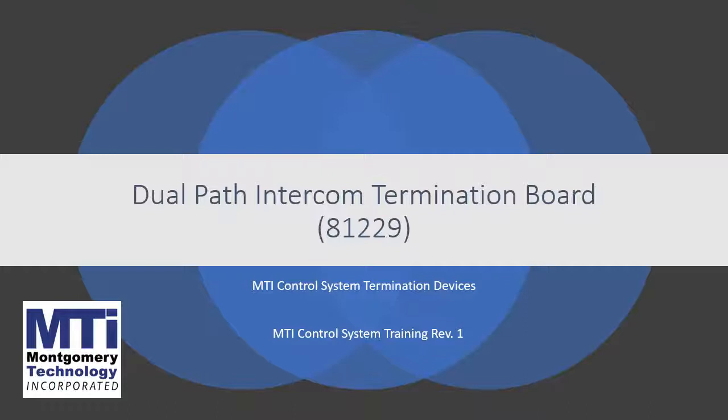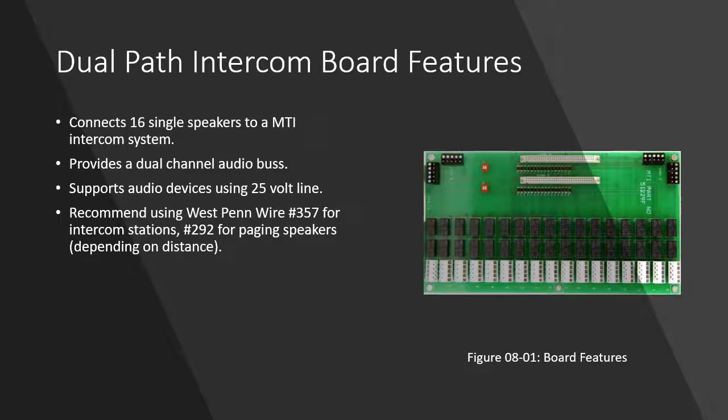In this session, we're going to cover the 81229 board, which is the dual path intercom termination board. The dual path intercom termination board has a number of features that are familiar to anyone who has dealt with any type of termination board on the MTI control system. All boards have the same behavior, having 16 single speaker inputs to the intercom system.